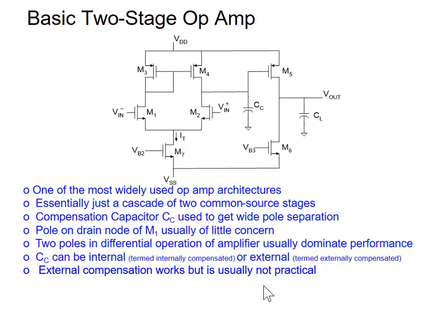This circuit we can also externally compensate. And it would be appropriate to externally compensate it if you know you're driving a large capacitive load. But usually if you don't drive a large capacitive load, you prefer to internally compensate it.